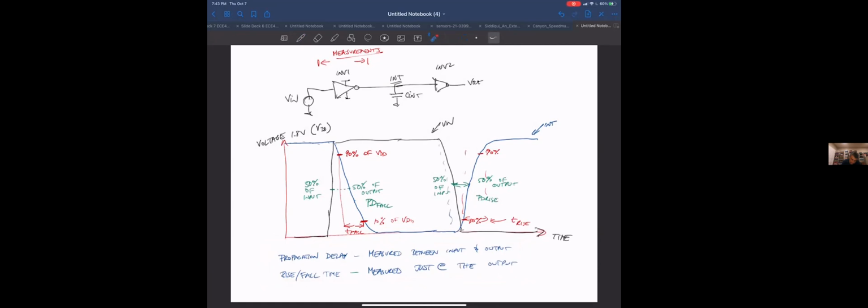By the way, this is just for the sake of completion in this book here. It's pretty typical that you define rise fall times as 10 to 90%. Some people define them as 20% to 80%, so people will tell you this is the 10-90 rise, this is the 20-80 rise.